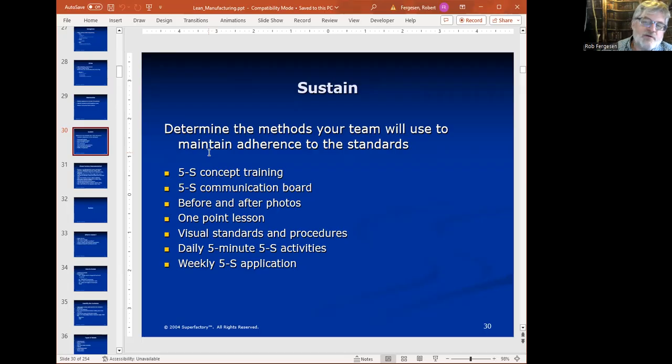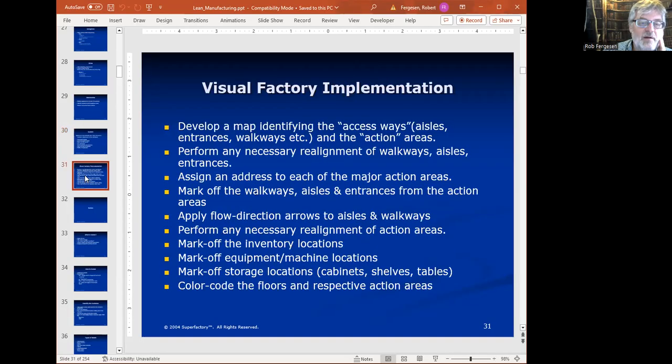You've got to make sure you've got a process in place for continuous support of new operators and new programmers to do adjustment of the work cell, robot points and the new PLC. People need to understand how that PLC program works, and you must make sure your documentation is good so that if a person needs to go in there and change something, they can find that change location very quickly and make the change without risk of screwing something else up in that system. So we're going to learn about the sustaining of a work cell following the basic lean methodology.